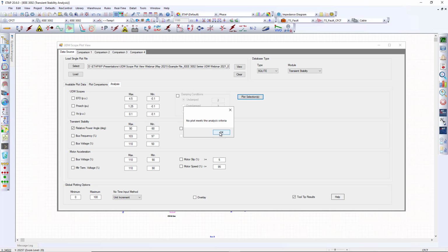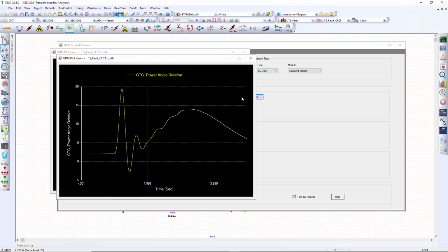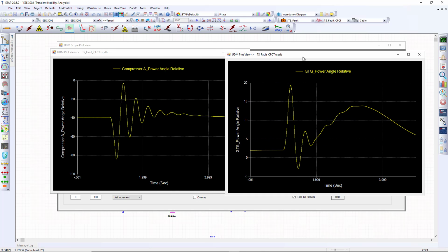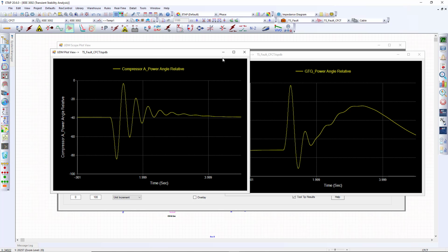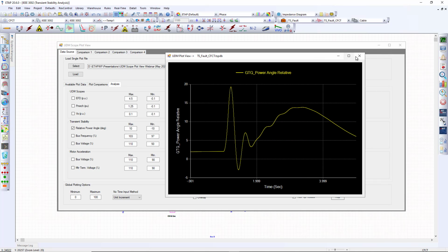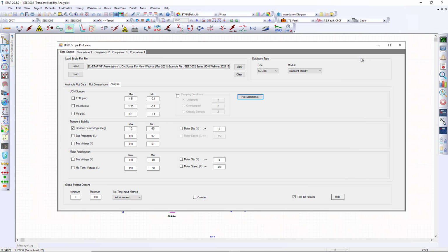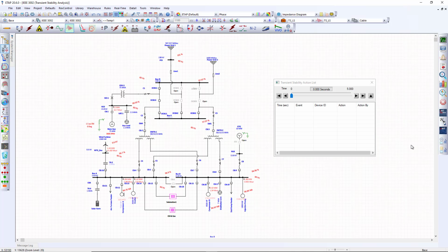that we have predetermined. If we reduce this stability range, let's say to 10 and minus 10, we can see the actual results from our system and how the synchronous generators are now in a much more stable operating condition after the fault is clear at 150 milliseconds. So we can say that we can determine and establish that the critical fault clearing time in this case is around 150 milliseconds.